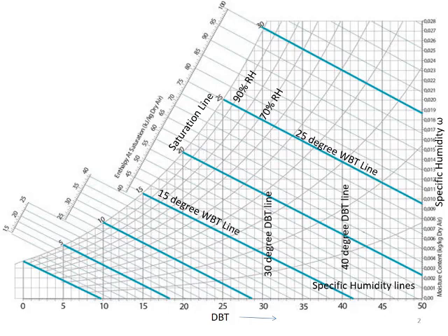Now there are some thin blue colored lines. At some points, these vertical lines may touch or intersect exactly at the point of intersection of those light blue colored lines on the saturation line. Then that blue colored line itself may represent WBT at a few temperature points, not at all points. For example, if you check 29, where it touches the saturation line is different from those light blue colored lines.